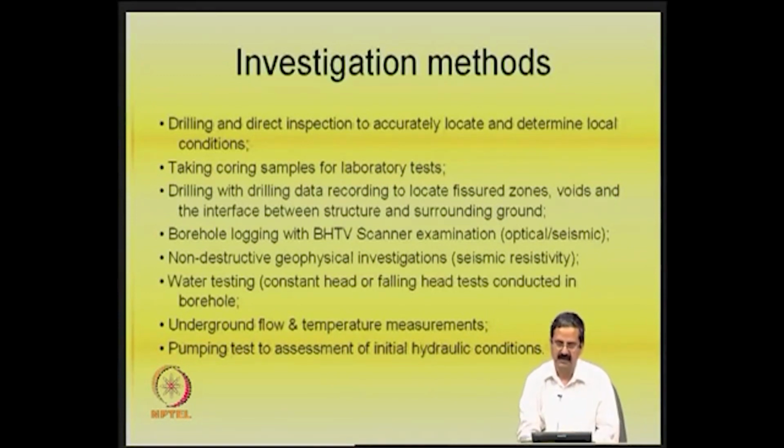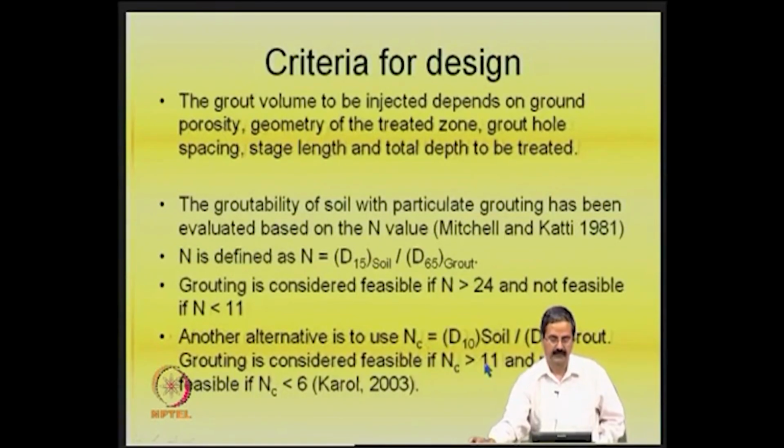So, temperature measurements are also important. Then pumping tests to assess the initial hydraulic conditions. As I just mentioned, grouting is very effective when the water table is there and all that. So, one needs to examine some of these conditions very carefully. The initial hydraulic conditions are to be known as well. There are certain design guidelines on how it can be done.